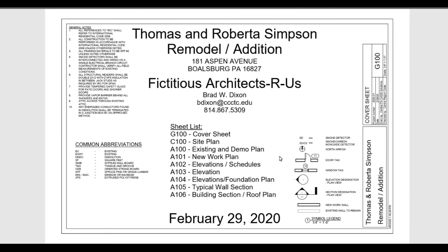It's very common to also have a list of all the sheets and what their names and numbers are on this title sheet, so you can very quickly look at a date on the set of drawings, and this is basically the date that the drawings are issued. And you can see that it's very different from the time that these are plotted and the plot stamp here that we talked about before. So this is used so that everyone's on the same page using the same set of drawings through the process.